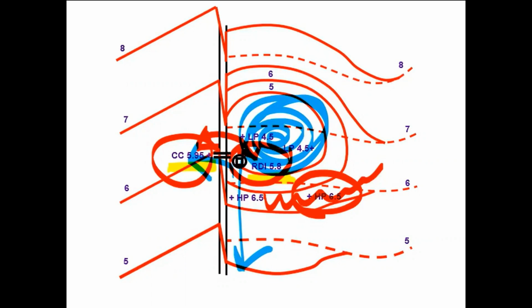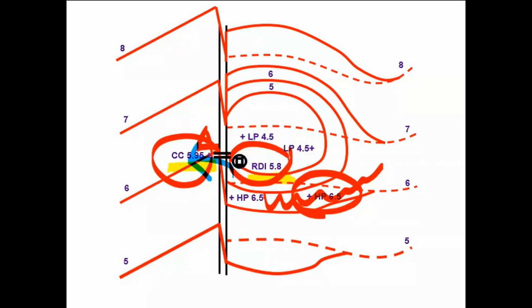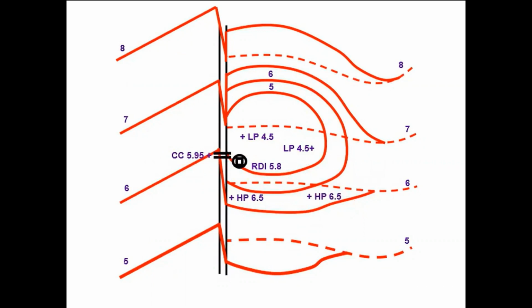there are a couple of rules that you have to know about the raised drop inlet in terms of its elevation. First, it must be below the berm, half a foot. Second, it must be slightly below the curb cut.